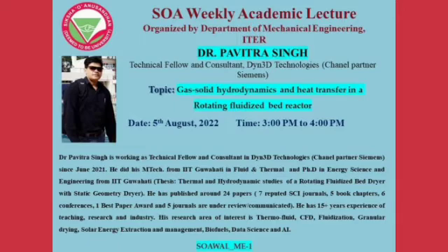So these are the parameters used in the simulation. So actually this is a multi-phase model, so that's why I applied the Eulerian approach with kinetic theory, and the time step used is 0.001 second, and the convergence criterion is 0.0001 for the momentum, and for energy it is 0.00001, and the under-relaxation factor is 0.5 for the pressure, 0.2 for momentum, and 0.2 for volume fraction and granular temperature, while the maximum solid packing limit is 0.63.